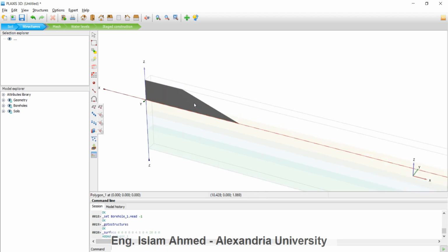That's our embankment here. Then we are going to make the construction stage for 2 stages. So we are going to divide this surface by a line from the half here to the half here. So we are going to the first for 0, 0 and 2 because it's 4 meter in height. Then we are going to 14 here, 0, 2.